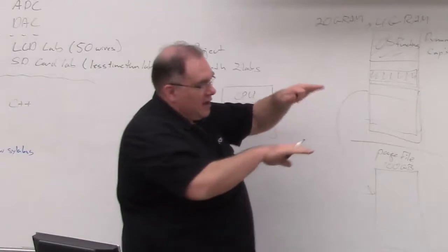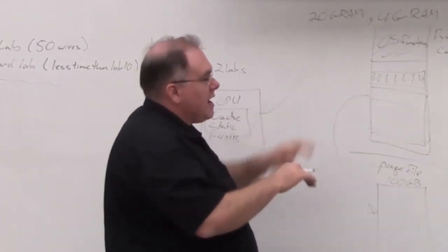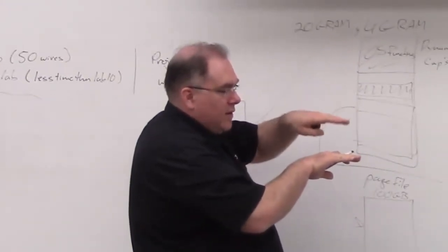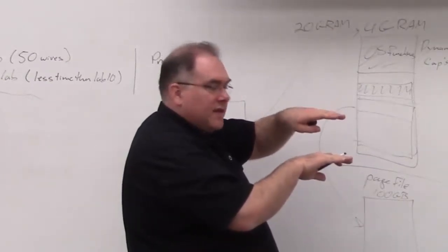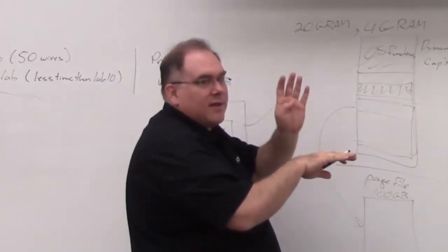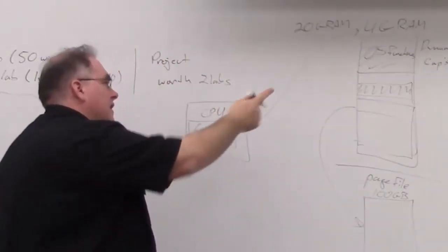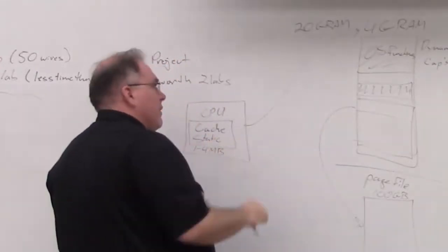Caps, they're discharging. So every once in a while, there's a dynamic RAM controller that has to go out, read that RAM, and refresh it. So it's dying, it reads it, and it will write it back to 1, right, to make sure it doesn't die. If it's a 0, no problem, right, because it's already dead. Right, so there's these little caps. A lot less expensive to build capacitors than transistors. Dynamic RAM is cheaper than static RAM.